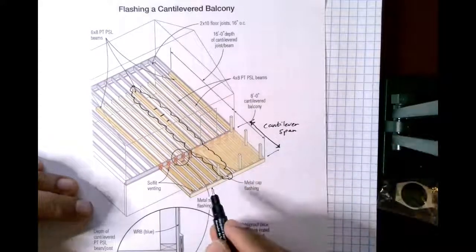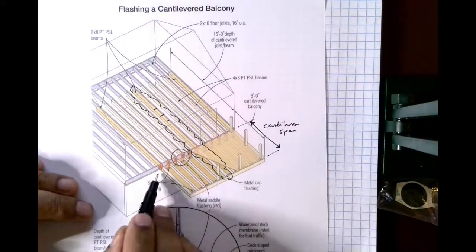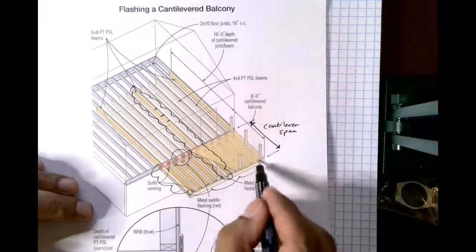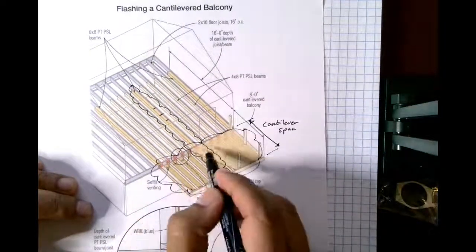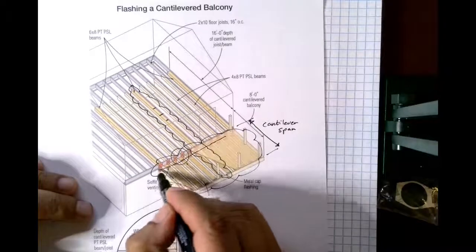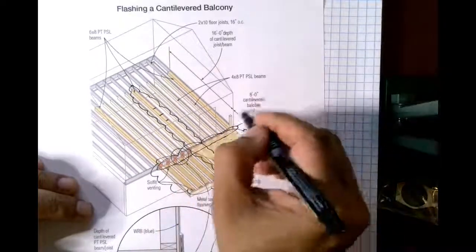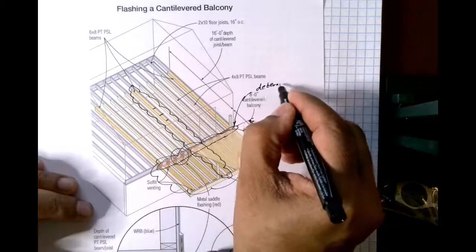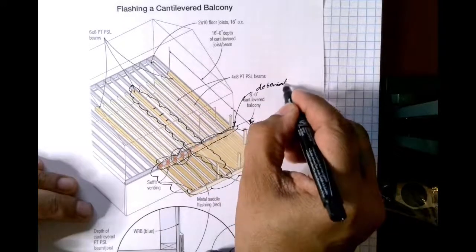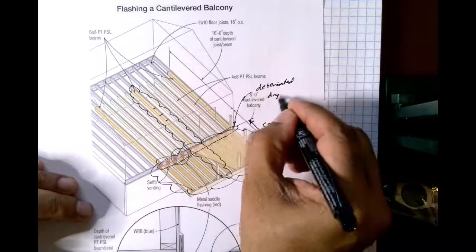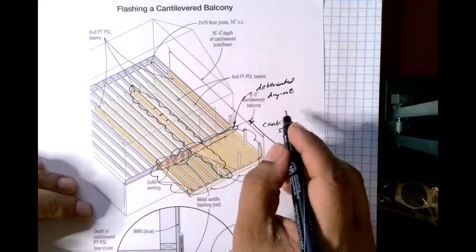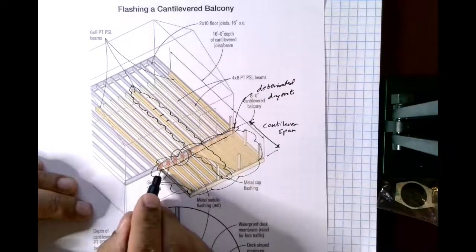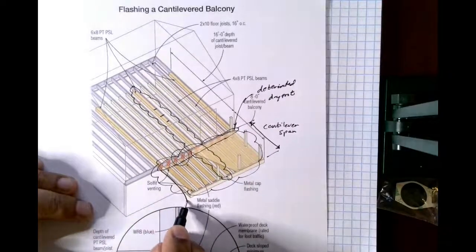And when we do a balcony inspection, what we're looking for is to see if this part, specifically this connection in here, has deteriorated. Does it have dry rot? Because if it does, then what will happen is that this portion of the balcony will deflect.